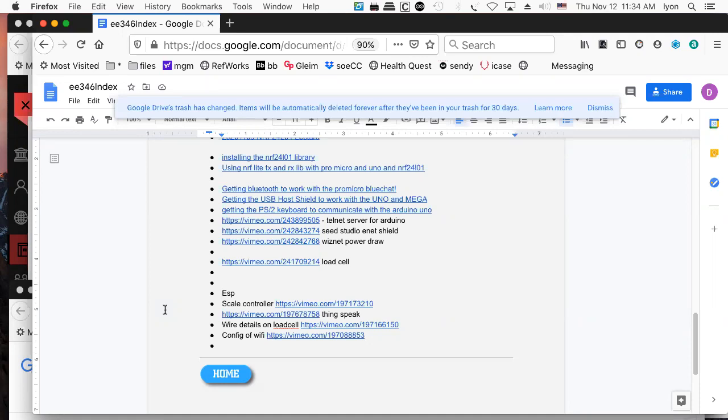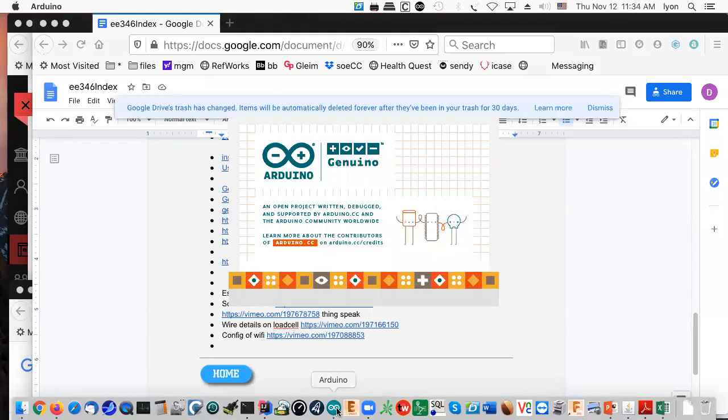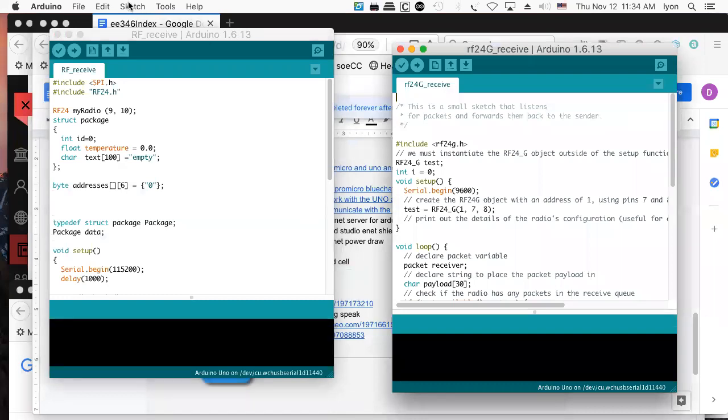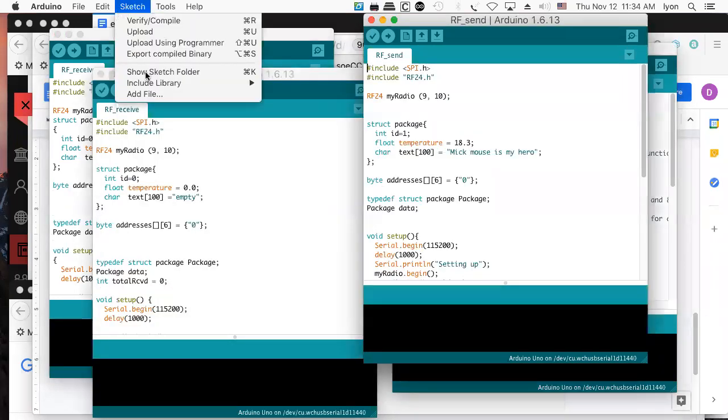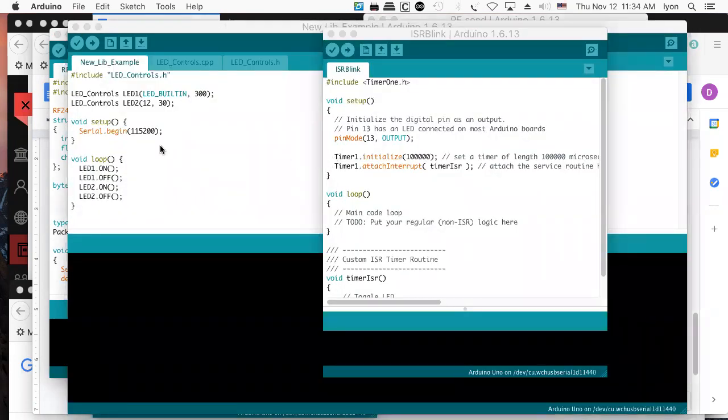So from the point of view of the Arduino, we have what I would call a suite of internet-based Ethernet tools. And that suite enables us to do all kinds of interesting things. You can gain access to that using the Sketch import library. I've already installed it, so it won't be particularly interesting here. But if you go to Include Library, Manage Libraries, and you type in Ethernet, you'll get a whole bunch of choices about the stuff that you can install.